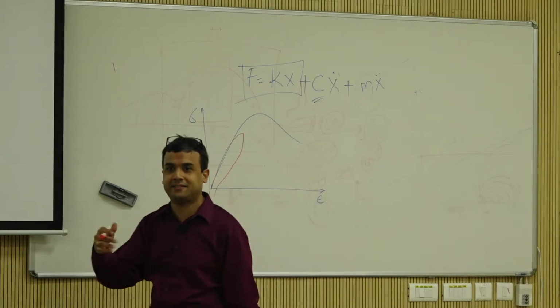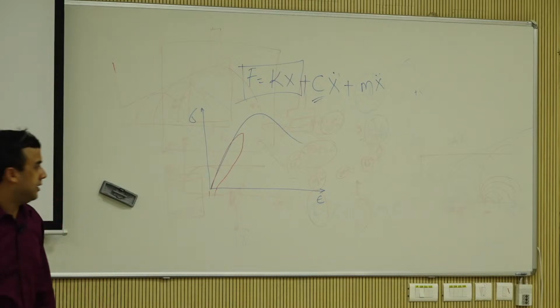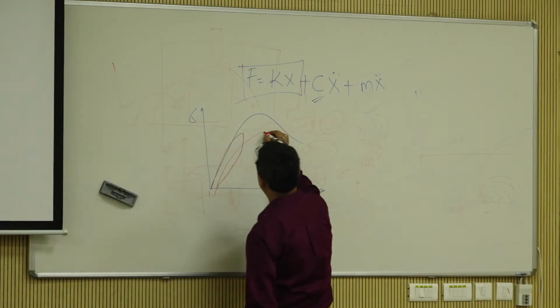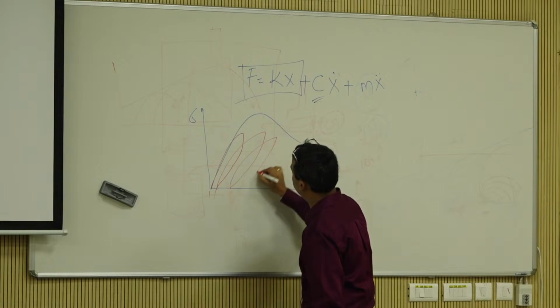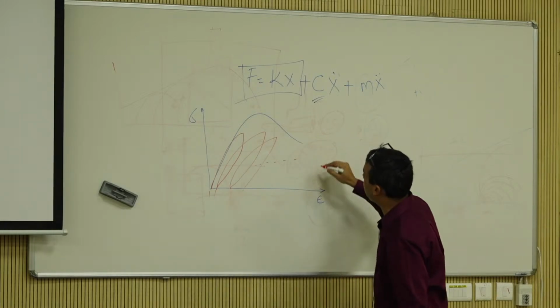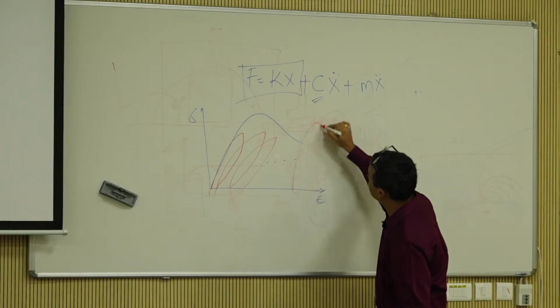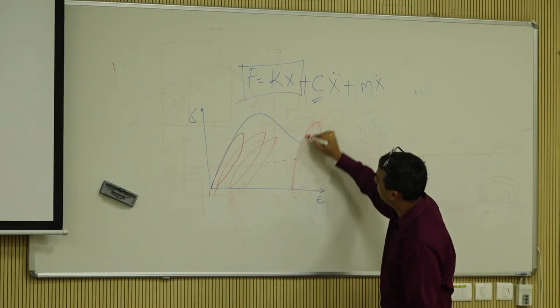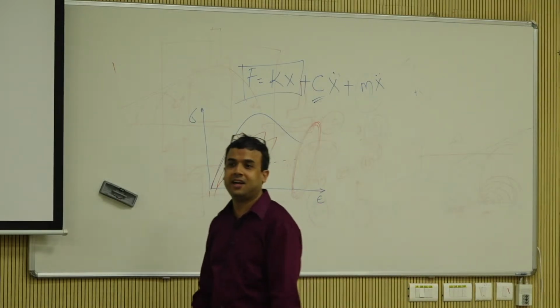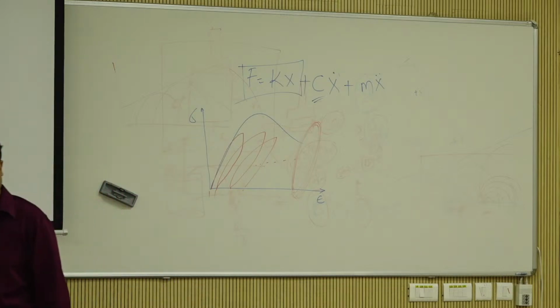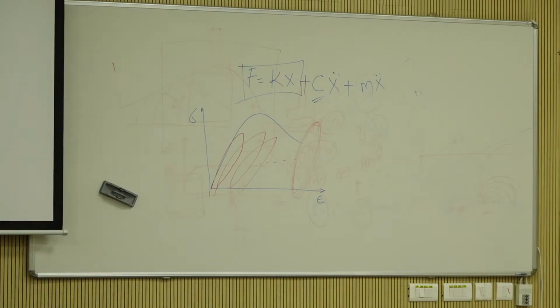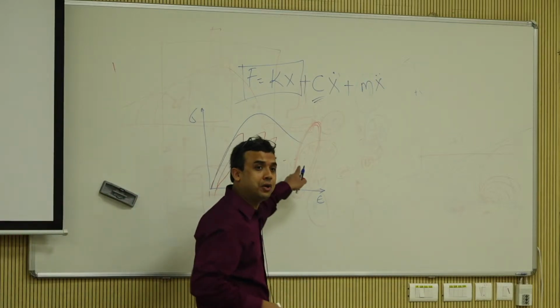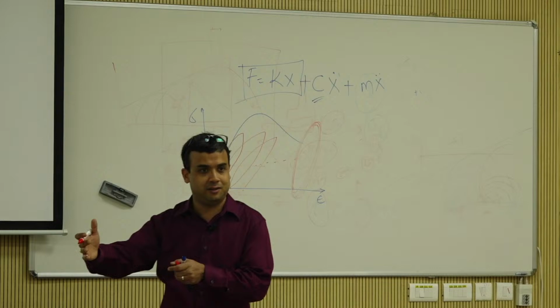It's going to have some plastic deformation, right? Next cycle, come back, do many cycles. At one point, you go into what is known as hysteretic behavior. There is no further permanent deformation accumulation. That elastic stage is what we are going to talk about, the resilient modulus and resilient stage.